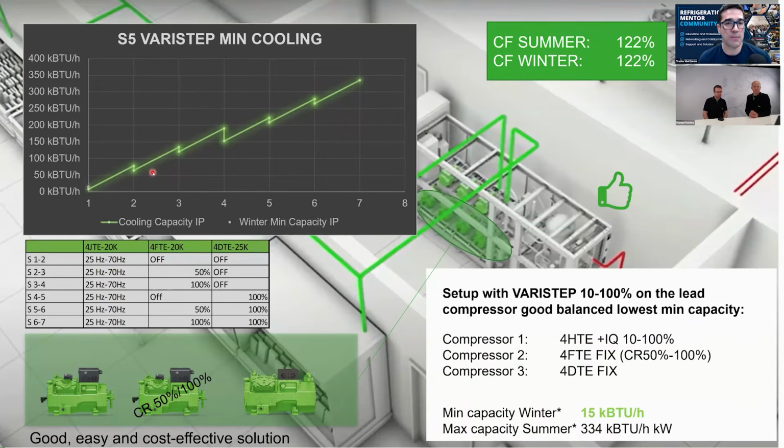So that's something you want to talk about with your customer, or if you're a designer or engineering firm out there, you want to have a good understanding. And most do today. The manufacturers I work with are real smart, so they understand the differences. But that's something you should think about with any rack or parallel system: why did they put this many compressors here? What is the capacity of it? And the biggest thing is the gaps as well. Like you said earlier, if you have a big gap and it's real low load in the middle of winter, a compressor bangs on, bangs off, bangs on, bangs off, then you get oil issues and lots of other problems, and not good quality of cooling. So it definitely makes sense.